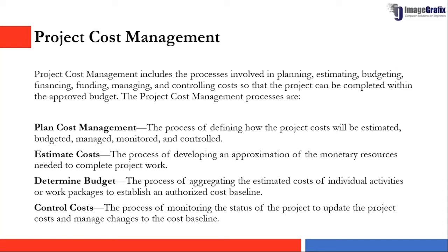But normally when we talk about cost management in the construction industry, currently most of them will be saying they are using ERPs, or they will be using P6. But in P6 we are not doing cost management. We are only doing the resource cost. We are allocating the resource, we are getting the cost, and we are assigning the actuals, and we are getting the actual cost. That's it.